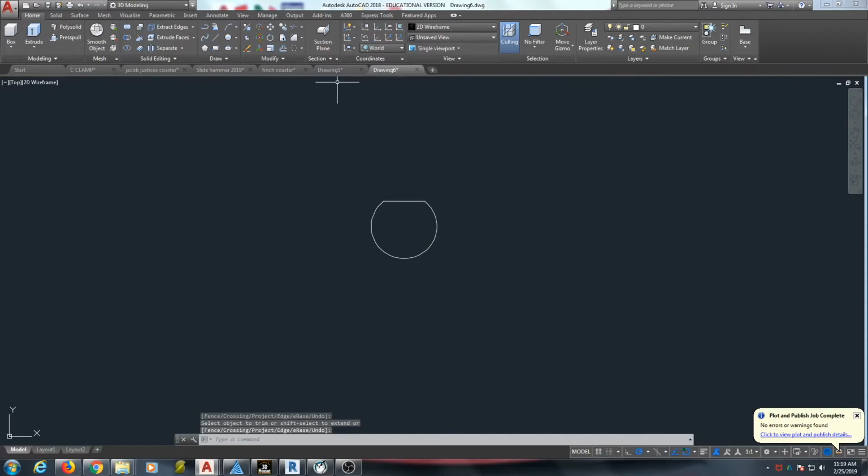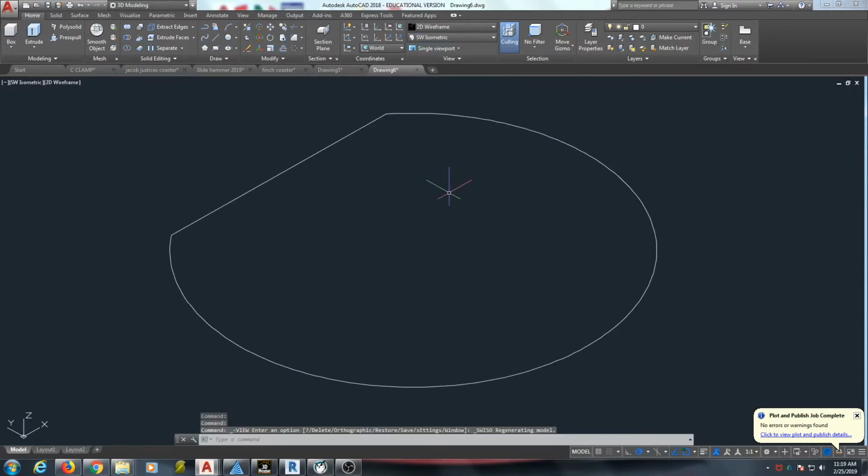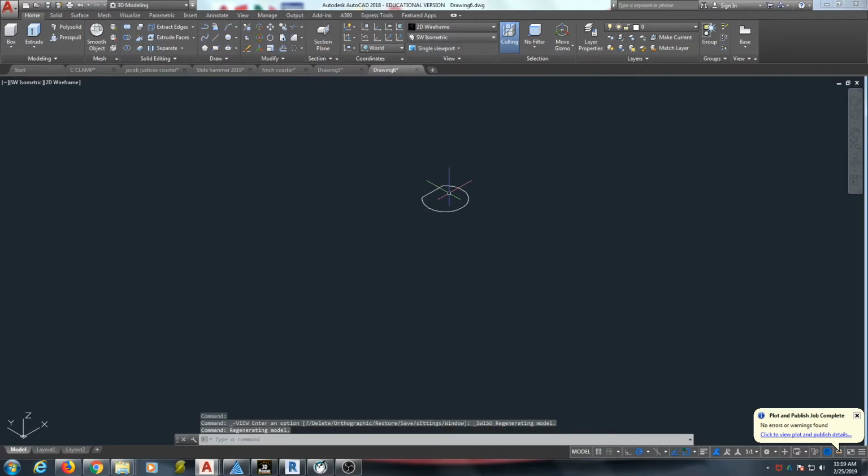The final step is to take and region the circle and the flat line that you made at the top together. And then you'll be taking and extruding it. The sheet says to extrude it over 600 millimeters. For our purposes, extruding this anywhere from 55 to 75 millimeters will be sufficient.